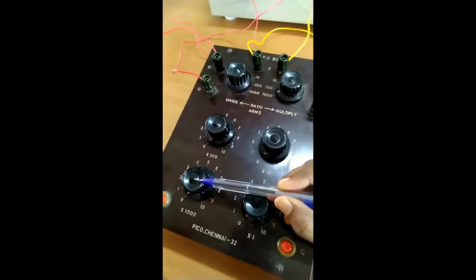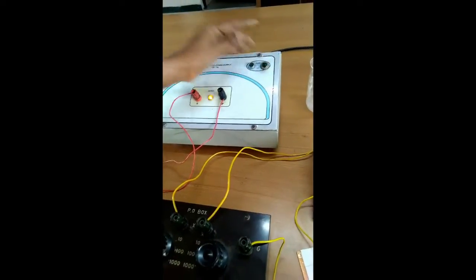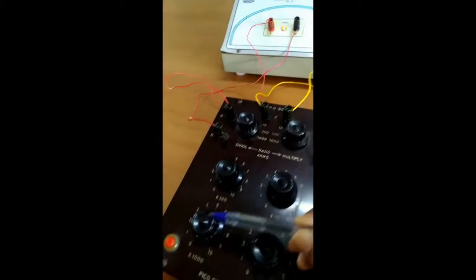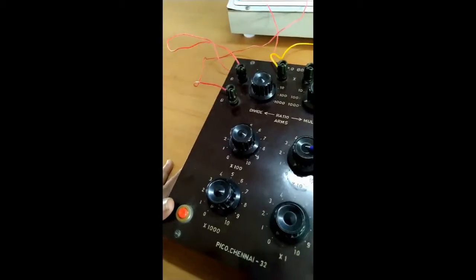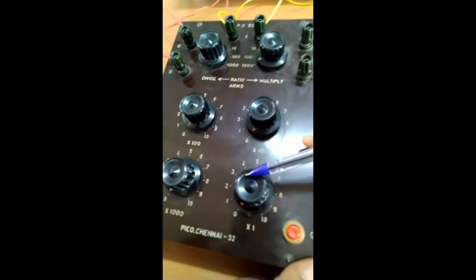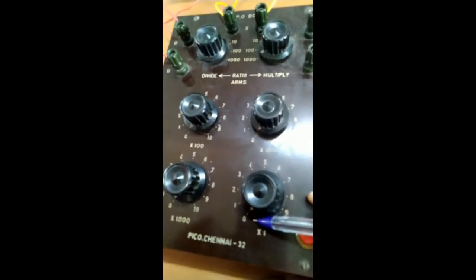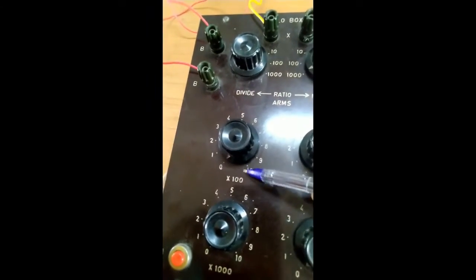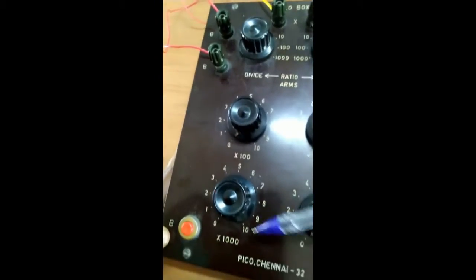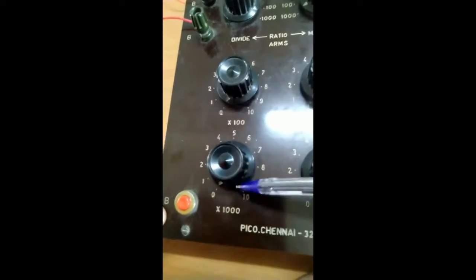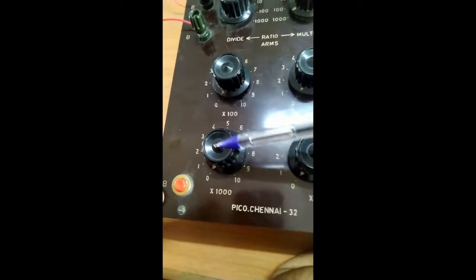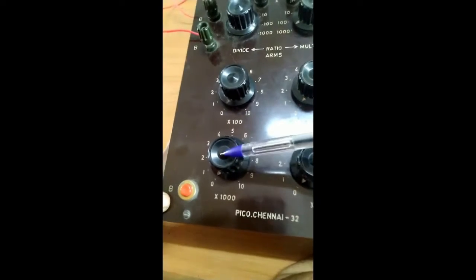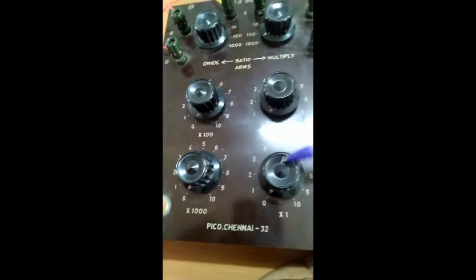First we need to click on this dial. Before that, let us switch on the battery. After switching on the battery, make sure that all these 4 dials are at 0 position. See here, it is 0. In the 10 dial also it is at 0. In the 100 dial also it is at 0. And in the 1000 dial also it is at 0. Now you need to set the resistances in the order of 1000, 100, 10 and 1.